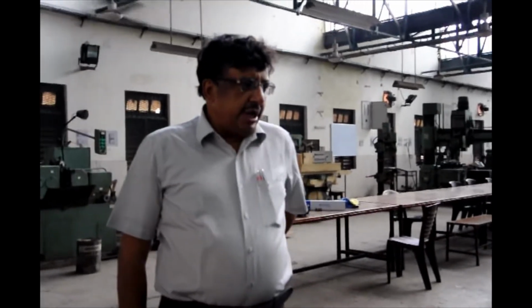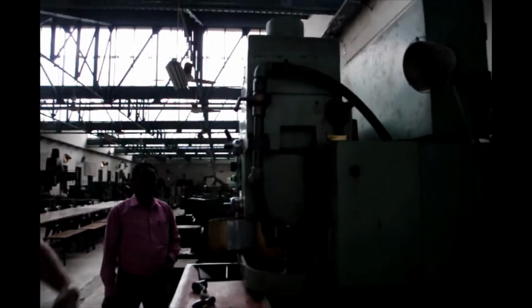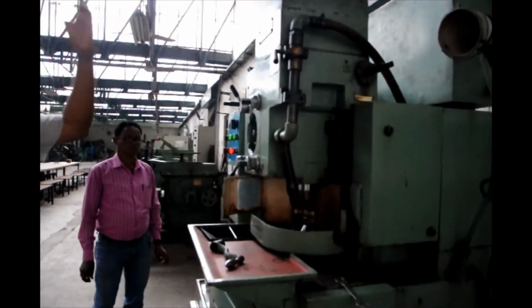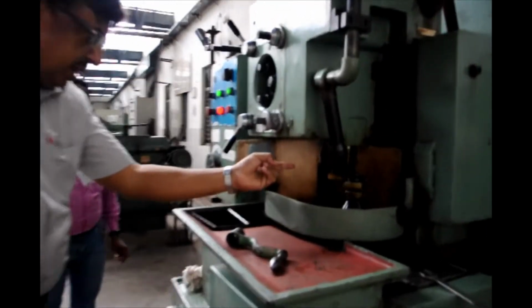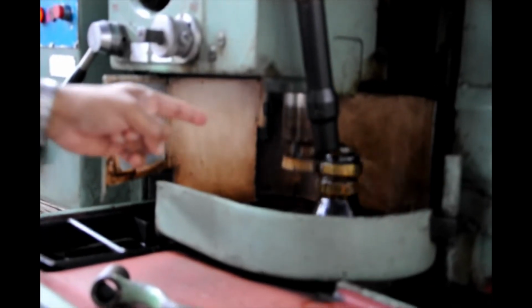Hello, good afternoon. Now today we will see how the gear hobbing and gear shaping operations can be carried out. This is a typical gear shaping machine. It is an HMT machine with the variety of AC150. So this is the gear cutter. It is a helical cutter, and that way the oblique cutter angles and other things are there. And here it is also responsible for cutting these helical gears. Helical gears have special purpose, and here movement is reciprocation of the cutter and movement of the workpiece is rotation.